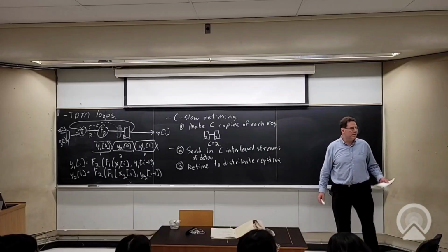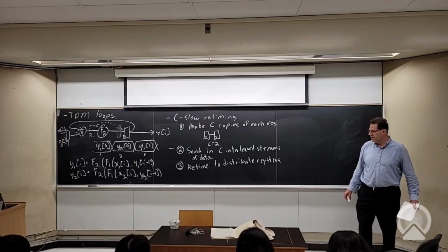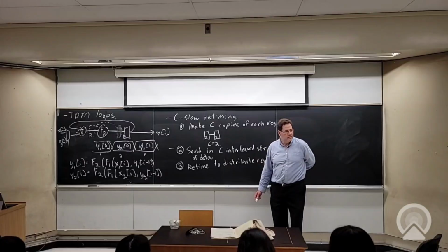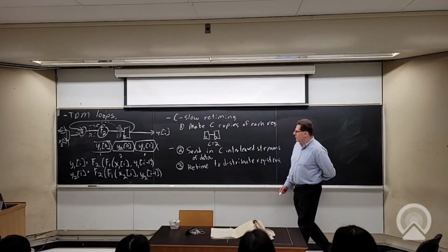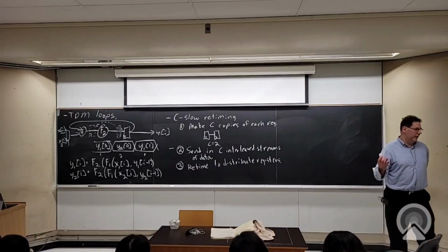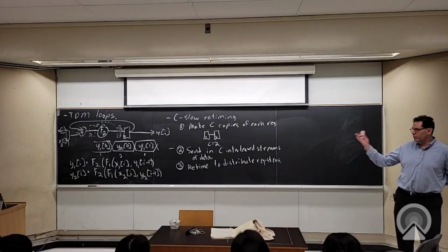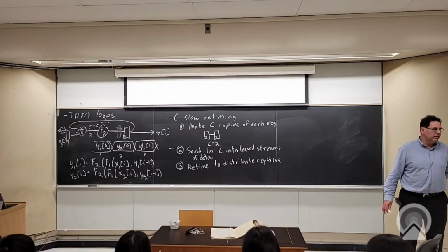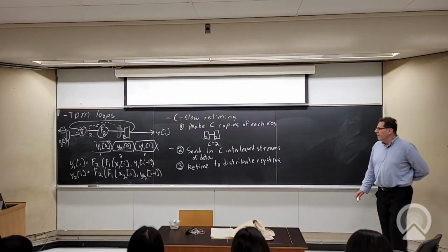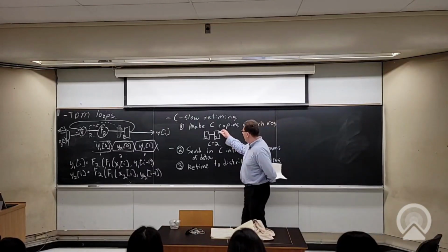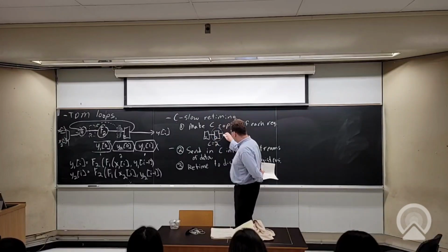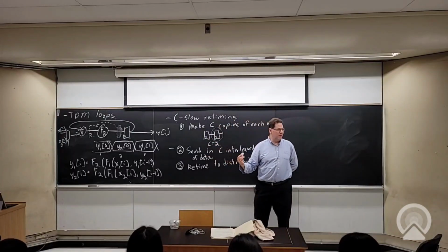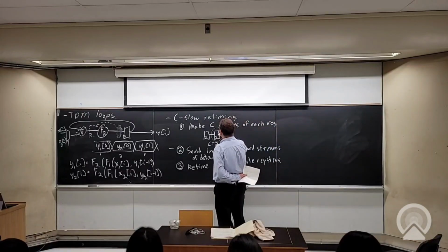I'm just slightly, not confused, but just the wording of the first step. We already had a register to start. Yeah. And you just made an additional copy. You made an additional copy, so I doubled the latency. That doubling of the latency is important in order for me to put in 2 streams and get the right behavior. So is it that we have C registers on the path, or is it making C copies, and you need 2 additional copies? For every single register you actually had in your design, so this was 1, you make C, well, I guess C minus 1 copies. Okay, so how do I write this? I see what you're saying.